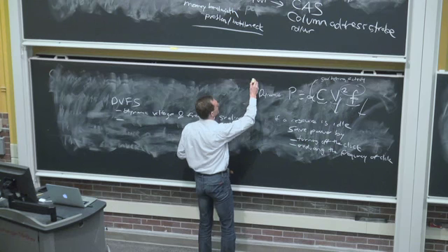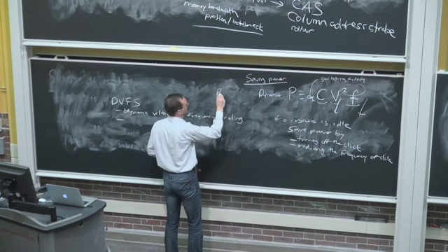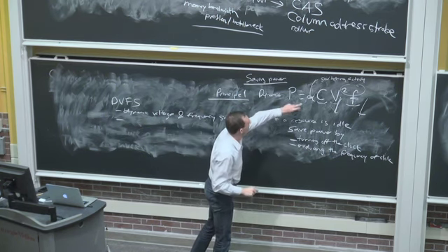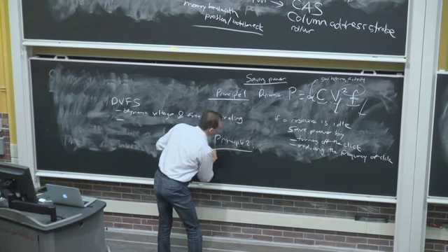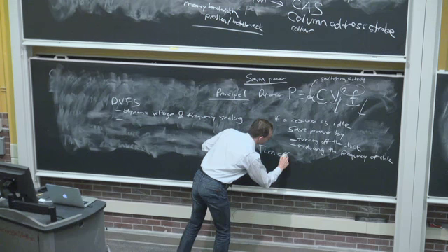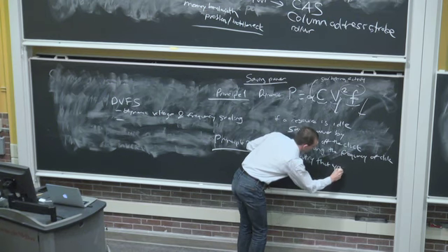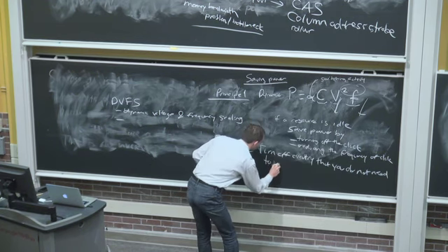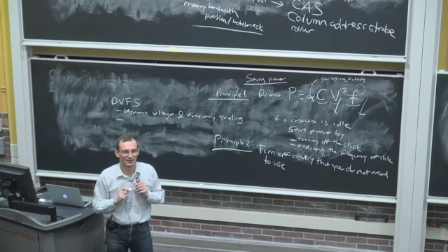That's one principle of saving power. I guess we're talking about power, so I'll give you the other principle that's employed in existing systems. Principle one, reduce the frequency and the voltage. Principle two, turn off circuitry that you do not need to use. For example, if you know that you're not going to use the floating point divider, turn it off. Right? Turn it off, what does that mean?